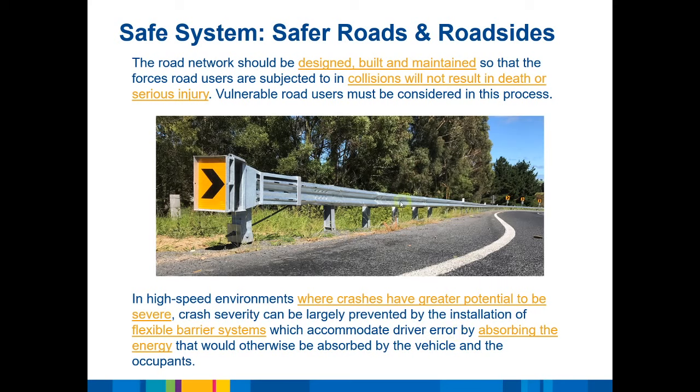This barrier is made of steel. I'll talk a bit more about the head-on treatment as well as the barrier itself, but steel is a very good material for absorbing mechanical energy in deformation, particularly if you have a hot-rolled section that has a great deal of ability to deform. So once it's struck, it's going to deform and change shape. It can change shape a tremendously large amount without breaking, without fracturing, and in changing shape, it's going to eat up energy. That's what it's designed to do. It's what these barriers are designed to do.